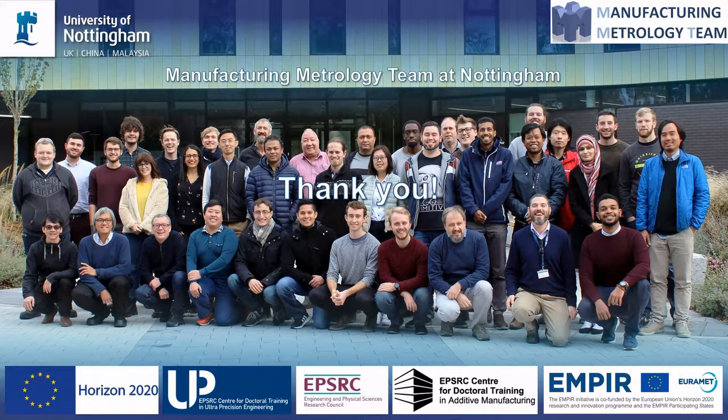After the calibration method, do you also do some kind of fitting, or do you just use the calibration? I use the ICP, iterative closest point algorithm, taking the first point cloud as a reference, and then the other point clouds. Since we still have some noise issues, we need to optimize it using the bundle adjustment approach, and after that we will generate the heat map and align with the CAD model.